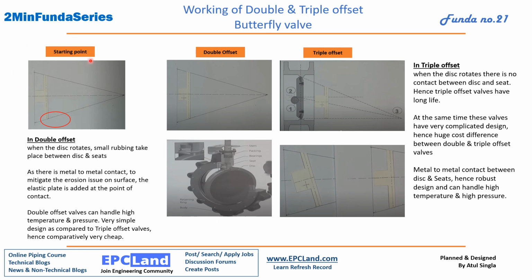If we start with this point, we have a butterfly valve and its disc inside it. Then we cannot rotate it, it will not move, because this point will obstruct with the seating. If we offset this center point from this point to this point, then there will be less touching area between disc and seat. This is the double offset type valve. But even so, a small portion will still touch the seat. To avoid this, here we have a metal seated valve.